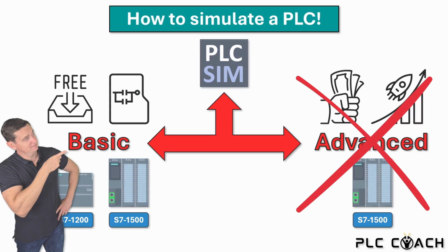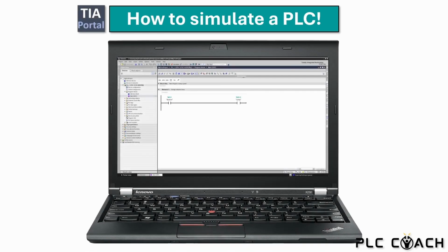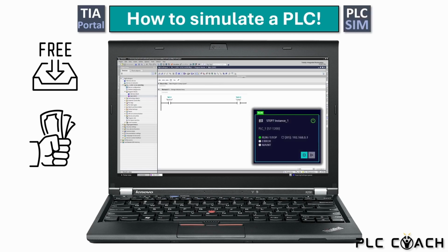Let's go! To learn PLC programming, the TIA portal is a must. You can use the free trial versions or purchase a full version. We have already discussed this topic in a previous video. PLCSIM allows you to create a virtual PLC on your computer. You can transfer your project to it and test your program. This software is free to download and no separate license is required. However, you do need the TIA portal to load your program into the simulated controller.